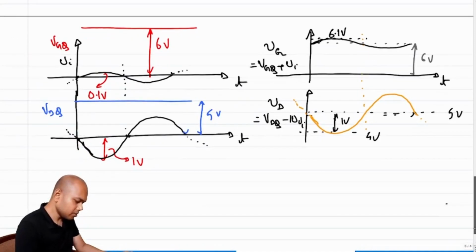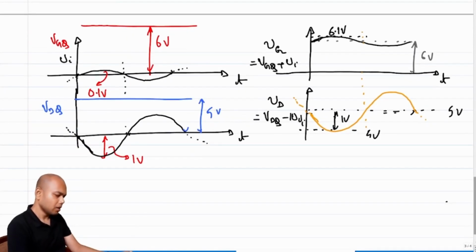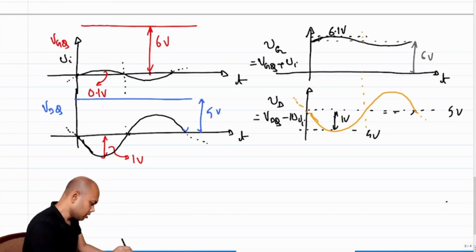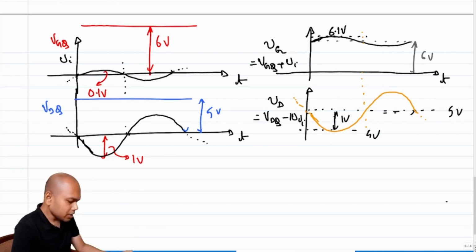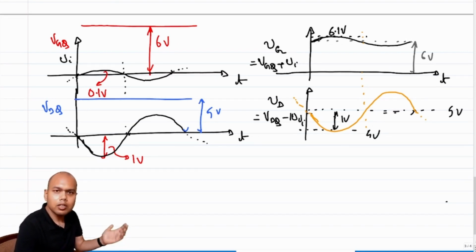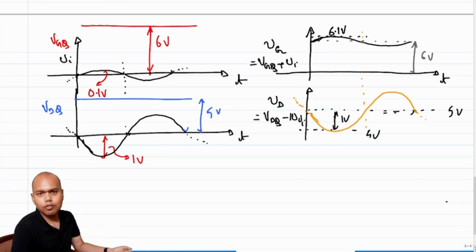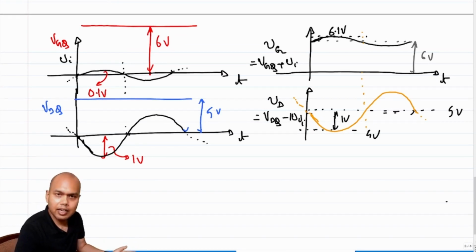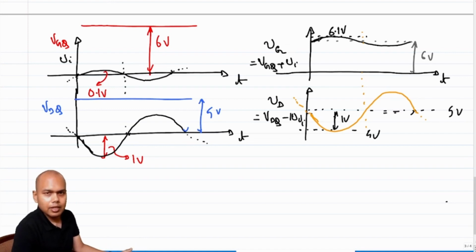Okay, so what is the solution? The solution clearly is the same old. The transistor is in triode, right? What we need to do, we need to raise the drain voltage, and what is the only handle that we have? The handle that we have is to raise the VD, right? So what is the solution?